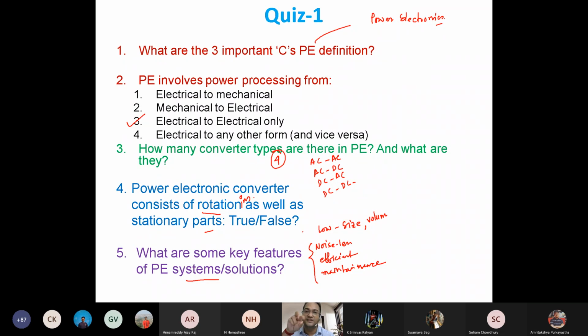And the small regulator that you see in your home, behind that there is a small circuit, of course. It is not only that white knob. Behind that there is a small circuit where an AC to AC converter is involved. So you can understand what we are looking for. We want a very small, compact solution which should be efficient. How do you understand whether a system is efficient or not? If there is a lot of loss in the system, it will develop heat. You know Joule's law, right? I square R T. Whatever current is flowing into it, it's RMS squared times the resistance of that element times time. That turns into heat.